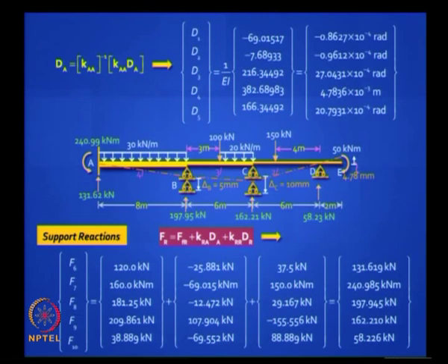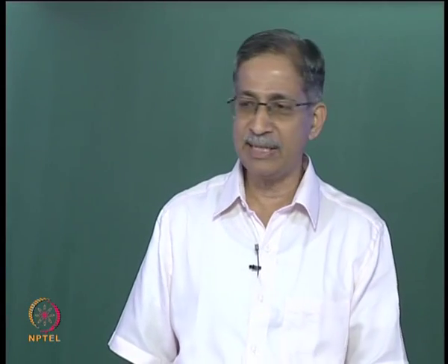Shall I proceed? You've got to see the reaction. So you show the reactions, see whether it makes sense. What's the next thing you should do before you proceed? You should do a quick check, because you might get funny results. What's a check? Equilibrium, at least one equilibrium. So add up all the loads, see whether they match. In this case, I think the total downward load is 550 kilonewton. You will find that the reactions also match.